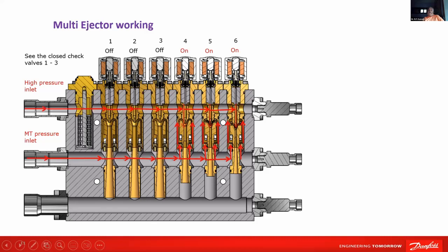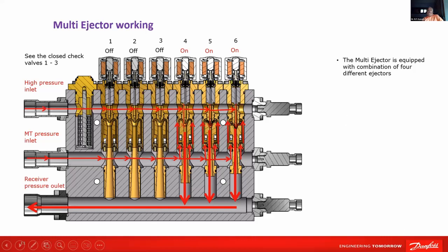Then these are having different capacities. So as per the capacities, we are able to adjust the flow required through the ejector. It's a combination of 4 different models: 125 kg, 250 kg, 500 kg, and 1000 kg per hour. Meaning in bigger ones, you will have 2000s here, 500 here. Some combinations are possible. Now we have basically 4 ejectors. The largest ejectors will always be placed in the beginning, and the smaller ones last. The smallest will be the last.